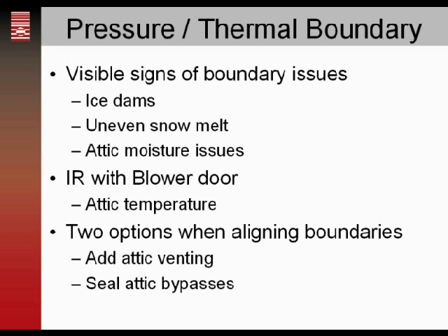So we've got two options when aligning our boundaries. If we add proper attic venting, we could, in this case, make that attic colder and reduce the amount of ice dams. Or we could seal the attic bypasses and make the attic colder.